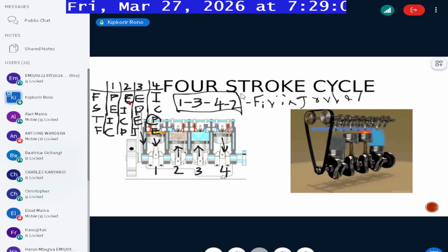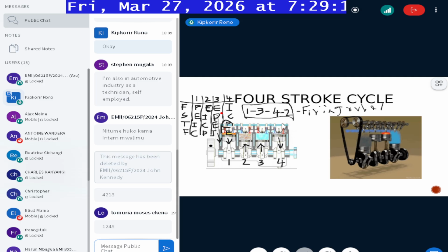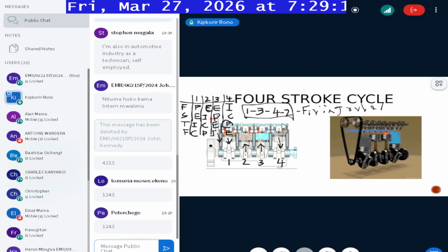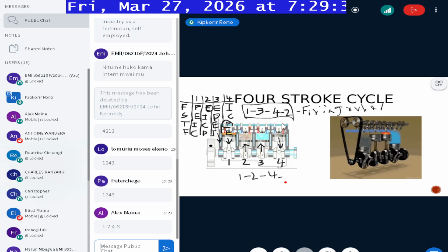Okay, I see John you have written 4, 2. No. The first one, we are not changing. The first cylinder will still be the first one to fire. So you are filling this, yes. Okay, Peter Chege, thank you. 1, 2, 4, 3. Yes. So it will be 1, 2, then 4, 3. So that will be the new firing order. Okay, thank you. So that will be the new firing order.